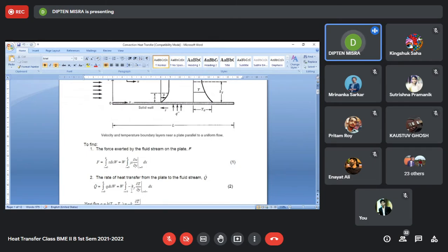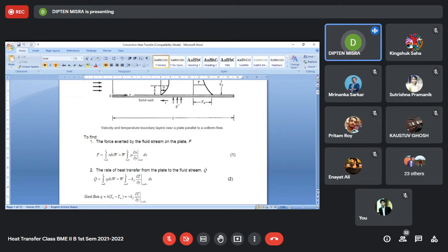So you get the wall heat flux, and once you know how the wall heat flux changes with x, you integrate this over x to find the total heat transfer rate over the wall, and you get the answer to our question. Now that is not our final question, it is an intermediate question so far as the convection heat transfer discussion of h is concerned.